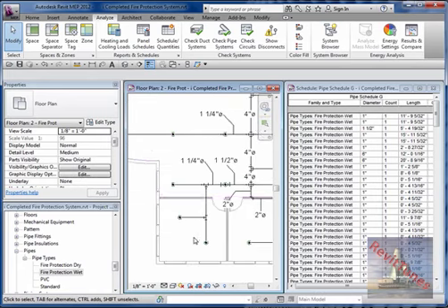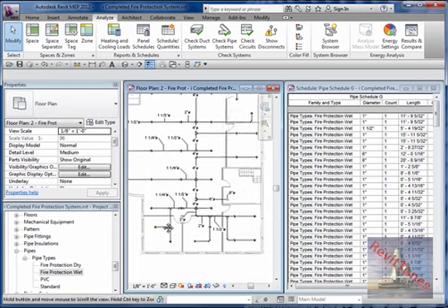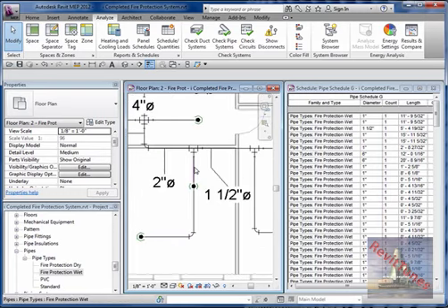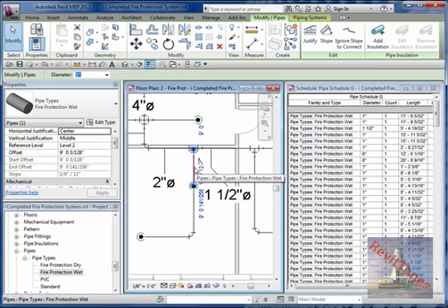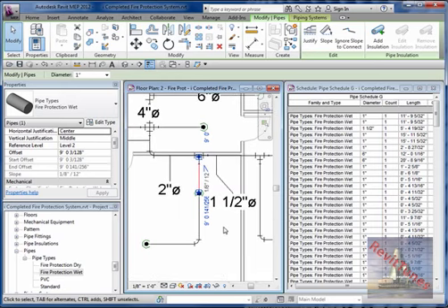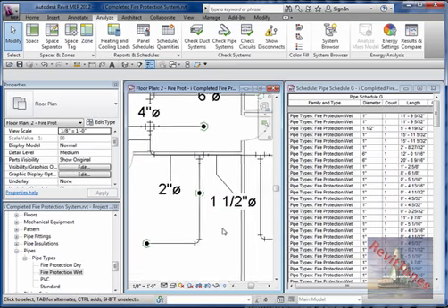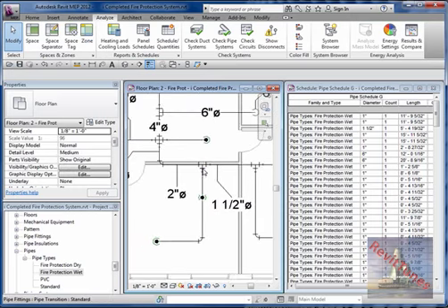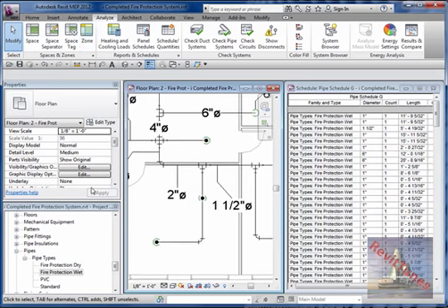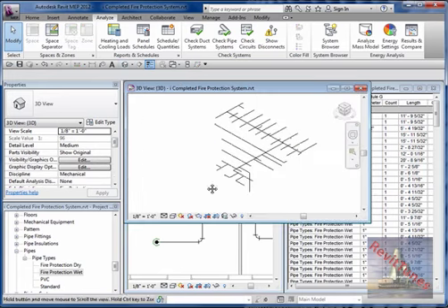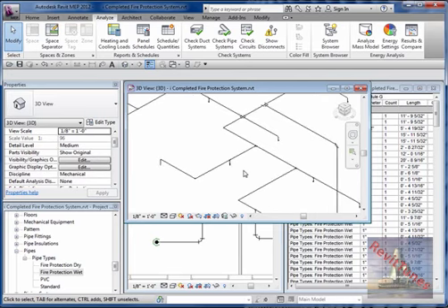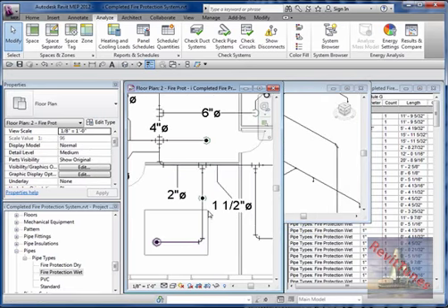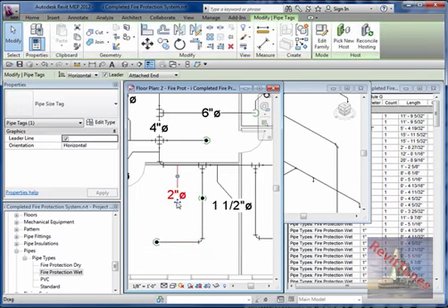Now remember, these pipes, no, actually these pipes are supposed to be from the dry system, and they are in the wet system. The reason is, when I created, I forgot to change the pipe type. So what I'm going to do, I'm going to erase those, and I will use the 3D view. In fact, from plan, I could just make a window. I'm going to move this tag to the side because it's in the way to do a window.